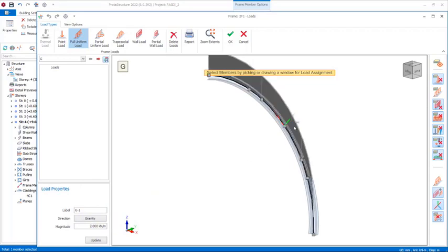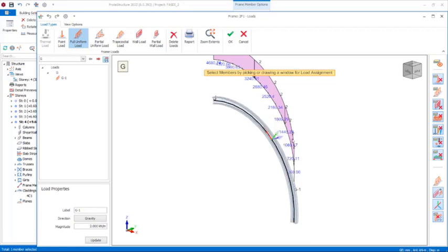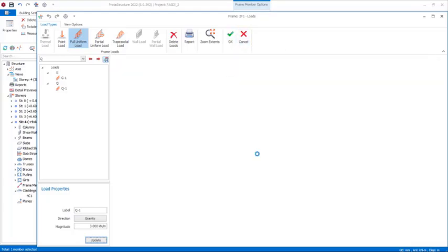Once you bring your hand over it like this, you see it's being selected. You just click it once. So here is the load. You can see 2 right there, for the G load. If you want to add the Q load, maybe you want it to be 3 kilonewton, you can just key in 3 right there and then select this, just like this. So with this, we have successfully added the necessary 2 loads on this curve beam. Click on the update option and then close.